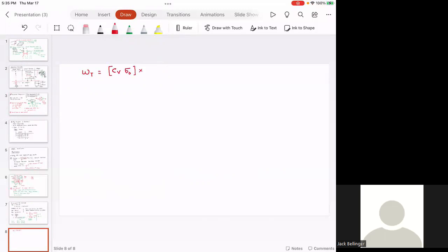I'm just writing the equation for the stress. Stress is equal to B multiplied by pi multiplied by M multiplied by Y. Remember, this is the beam strength equation. Y is equal to 0.124 minus 0.684 divided by T, so 0.124 minus 0.684 divided by 25.